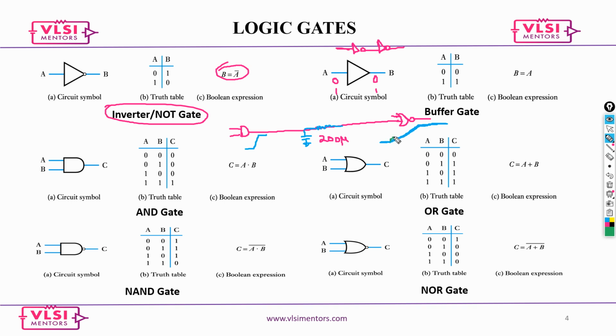For that purpose, we need to add a buffer. Where do we add a buffer? We might add it in the middle. Now it picks up the same signal that is coming over here, and the quality of the output is improved. So overall, the transition is improved. We need a buffer to maintain the transition. That is as simple as that.